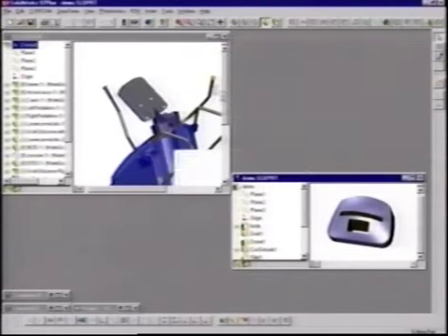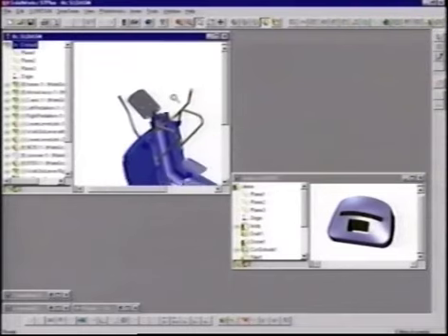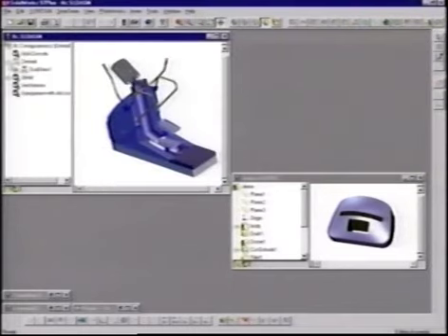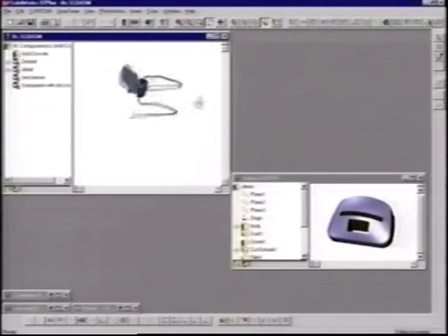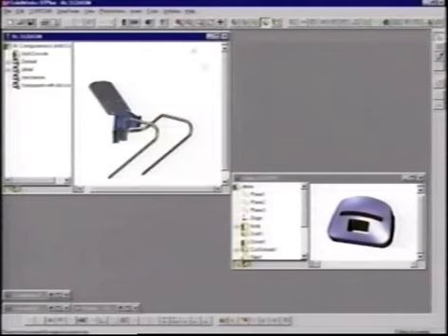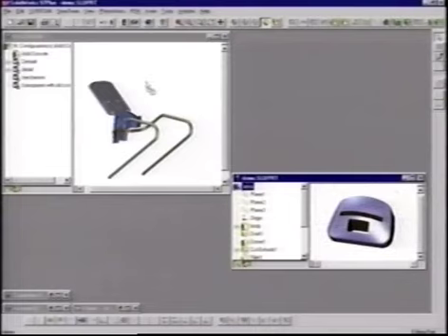Now what we'd like to do is take this console front that Joe's been modeling and add it to our assembly. Before we do that, Joe's going to use our large assembly management tools, called configurations, to simplify the assembly. This way we're going to zoom in or zone in just on the console area of our design. This is the faster way to interact with the design by getting rid of components we're not really interested in at this particular time. So like I was just saying, let's take that console now and drag it into the assembly.